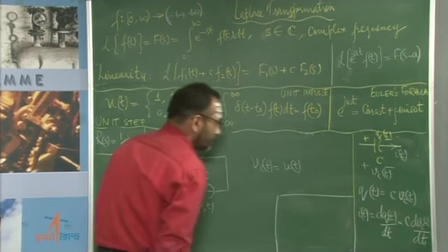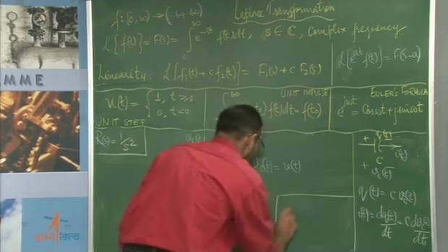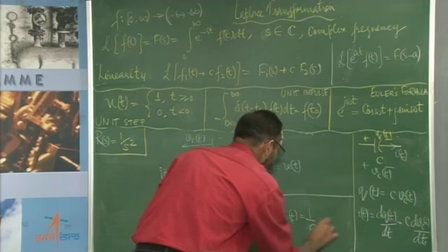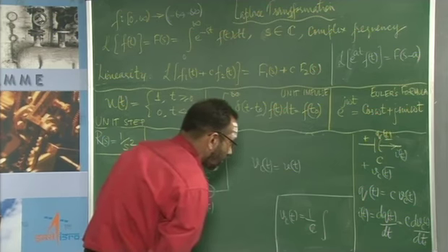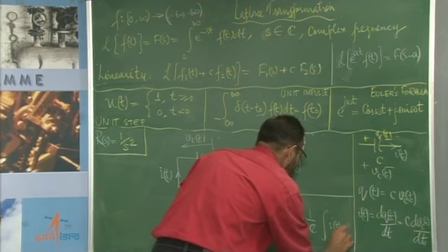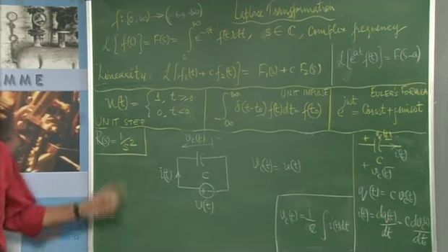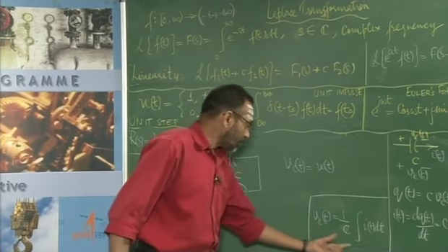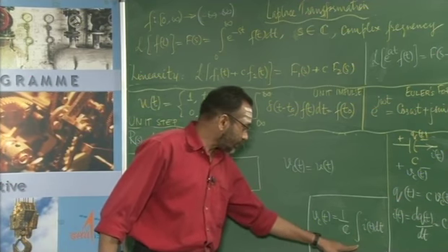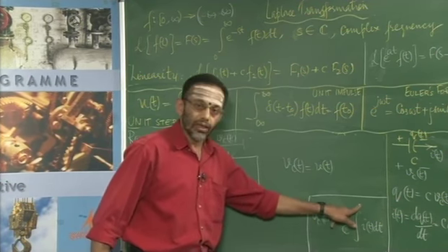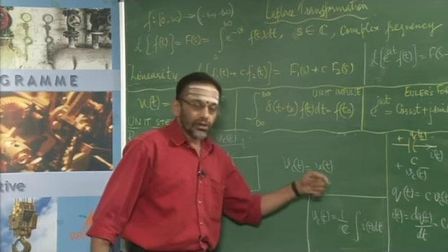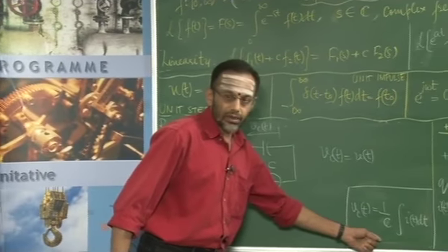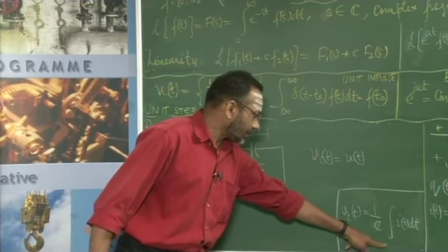All right. Now, with this, the usual mistake that we find in several places, several students are misled like this. The usual mistake is, now if I want to get Vc of t, they write Vc of t equal to 1 by C integral I of t dt. Now, there are two problems in this expression. The first thing is, this is a function of time, whereas on the right hand side you have an indefinite integral, which means you do not have the limits for these two. If you write an indefinite integral like this, you are going to get a constant of integration. That is not given here. Therefore, this is not the correct way of writing it.